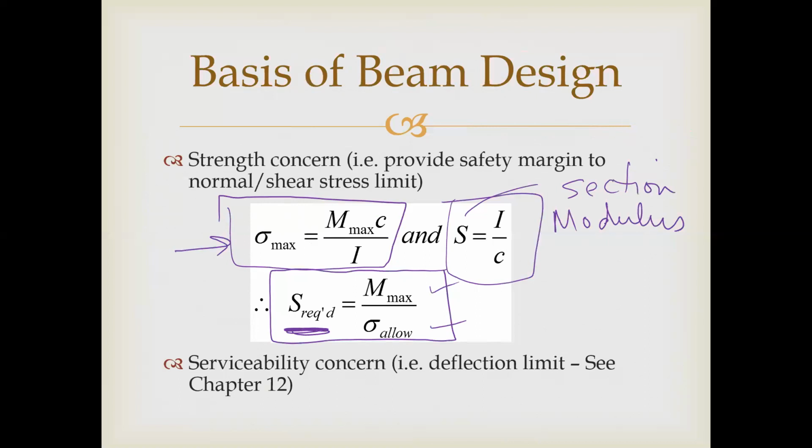You also are going to have deflection limits as well. So all of our codes for structural engineering have amounts of deflection that a member is allowed to experience. And so you could go through the same procedure where essentially you need to pick an appropriate I value so that that equation for deflection will not exceed what's allowable.